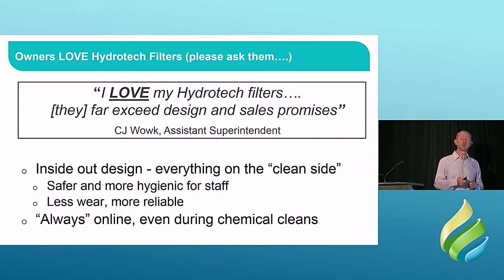This is an honest quote that a guy said to me. He said he loved his Hydrotech filters, and I really don't hear that very often from operators. So I'll stop there. I'm not getting anything thrown at me yet. So yeah, they work well. People like them. It's partly that inside-out thing. When you open the lid and you've got to work on a nozzle or change the drive chain or whatever it might be, you're in clean filtered water, much more hygienic. Less wear on those mechanical components, on the seals and all of that. So they hold up pretty well, pretty reliable.